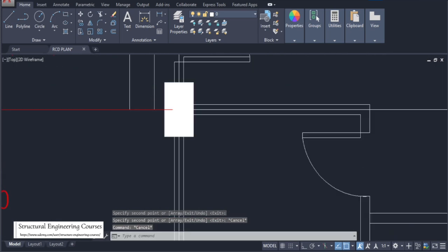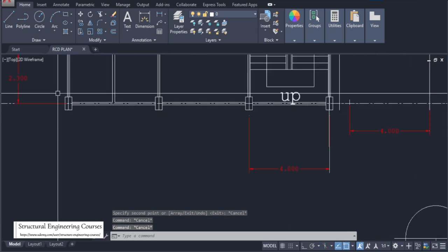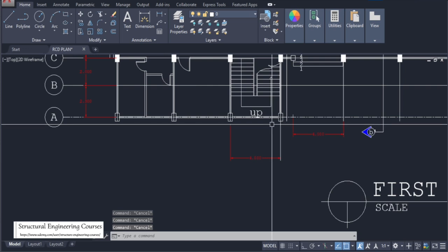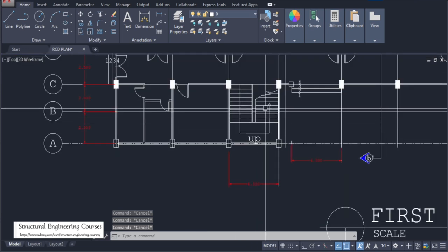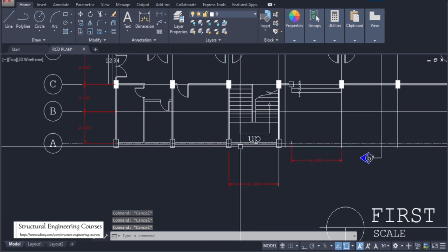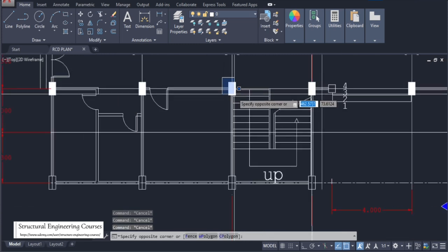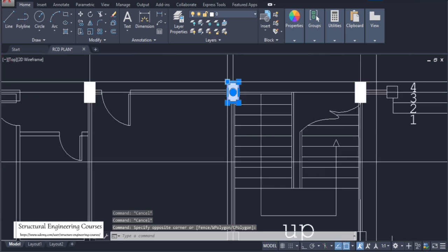So now we have planned this whole corridor area here, and then after that we can provide columns here also. This is basically the staircase here. So we shall provide a mid landing beam here, not a floor beam here. That is something we need to take care of while we are modeling the structure.